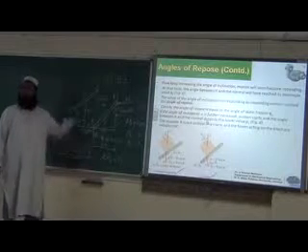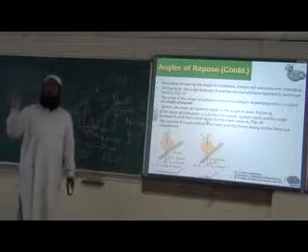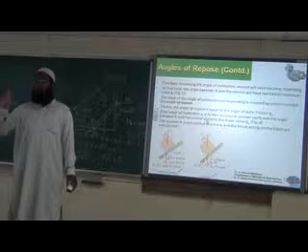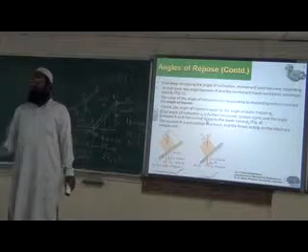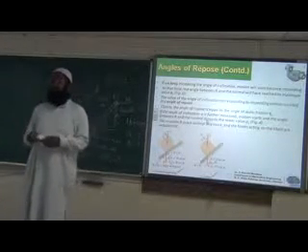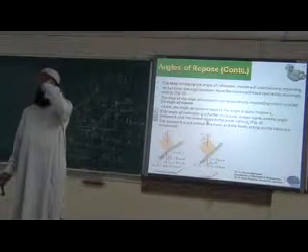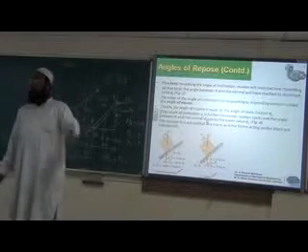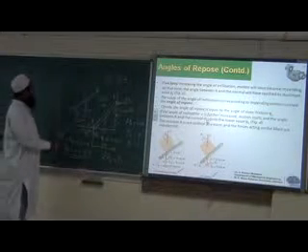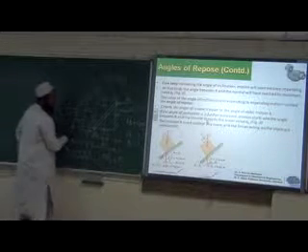So instead we go for the third equation, that is the sigma M equation. We have three equilibrium equations for a coplanar system: sigma Fx, sigma Fy, and sigma moment about any point of our interest, that is, moment about the perpendicular axis. If it is a three-dimensional system, we have six equations: sigma Fx, Fy, Fz, and moments about the three axes. Okay, so we have three equations now, since it is a coplanar system we consider. So we use sigma. I erase this.